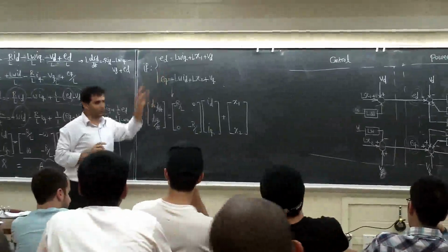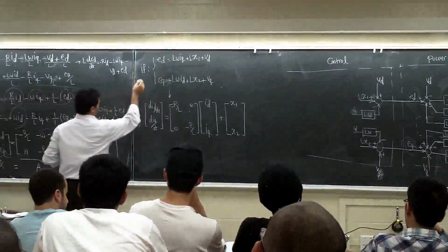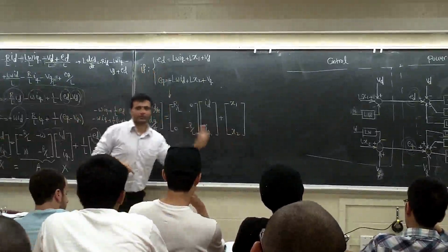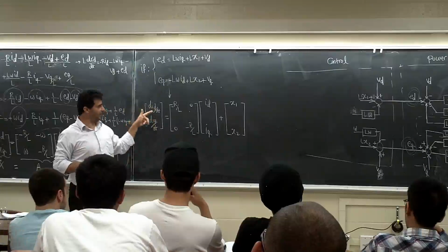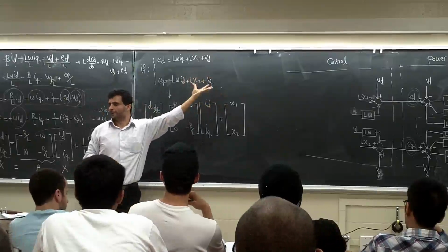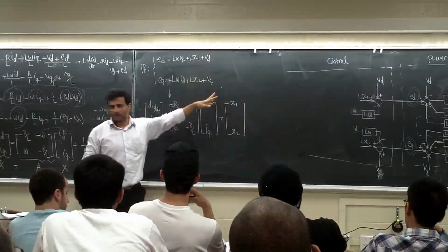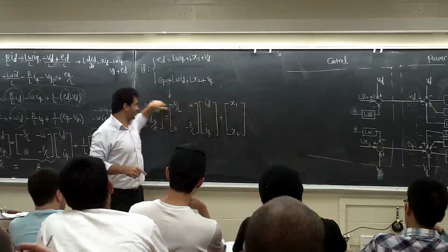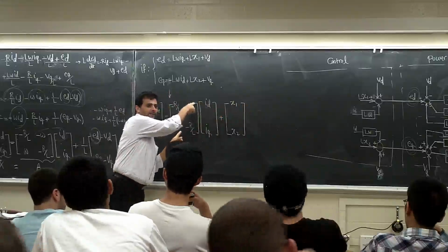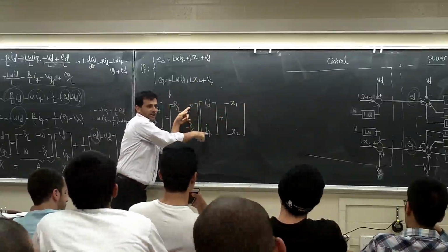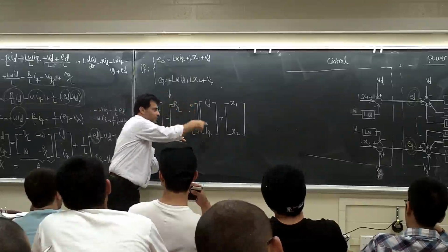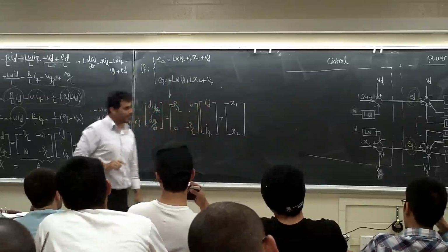If you replace these two, we select this one, replace it in this equation, this is a decoupled system. You got here dID over dt is minus R over L ID plus x1. x1 is an error from somewhere. There is no IQ anymore. ID is ID. They call it decoupled. See here? This term couples into the IQ, right? We made it 0 by selecting it down. This term will couple this Q axis to D, right? We got rid of that one.